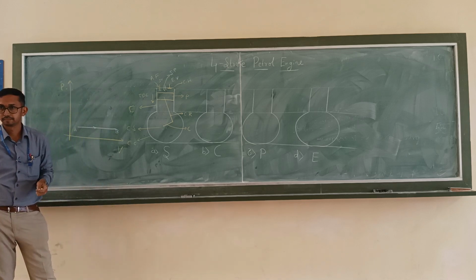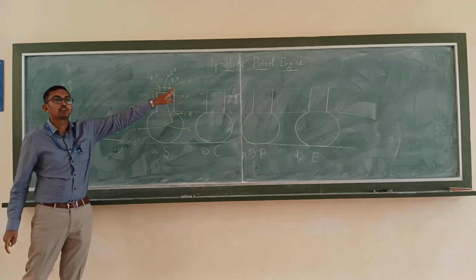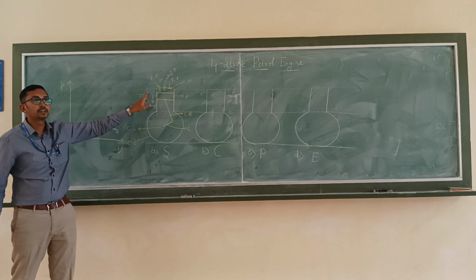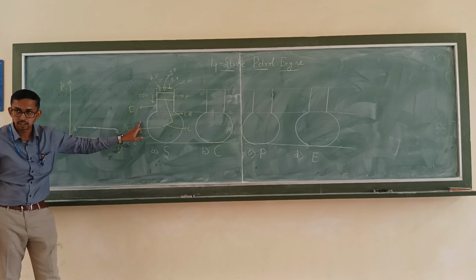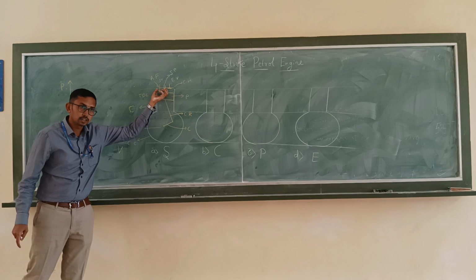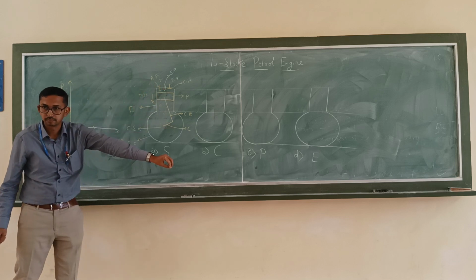Is it clear? The piston is going to move from top dead center to bottom dead center. During that, suction will be created in the cylinder, and the fresh air-fuel mixture enters the cylinder.